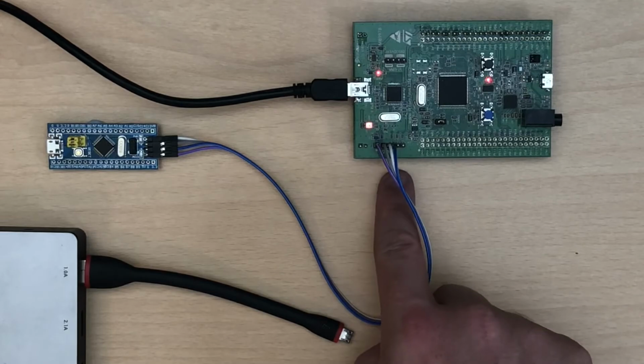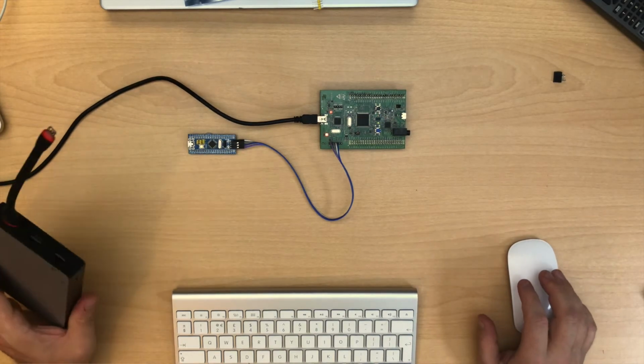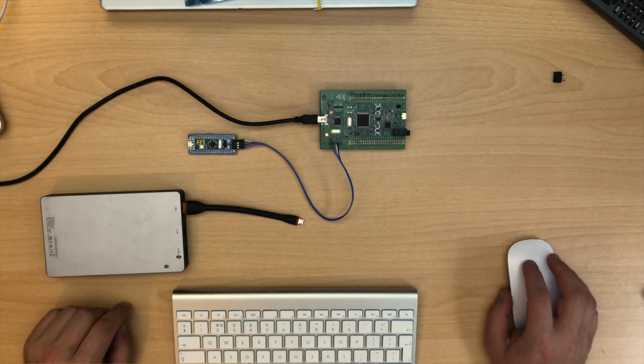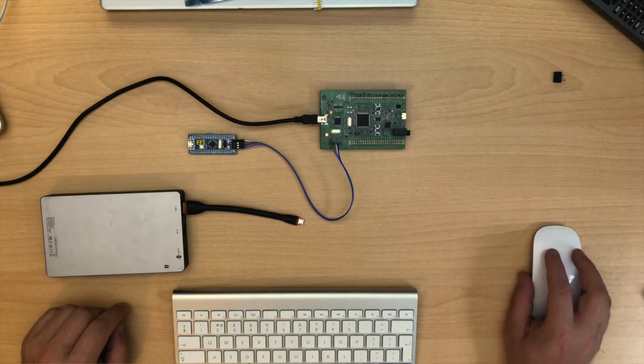We'll have a look at the connections here that we've made. So on the SWD device, we have this header, which has some various bits and pieces, and we have the little header here. We'll show you in the diagram how this is connected up here. I've just used a couple of little jumper leads. I have a power supply as well, because we want to separately power our BluePill whenever we're doing the programming and so on. But the first thing we'll do is create a program.